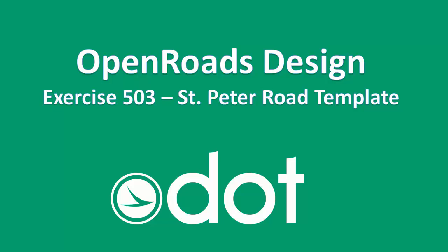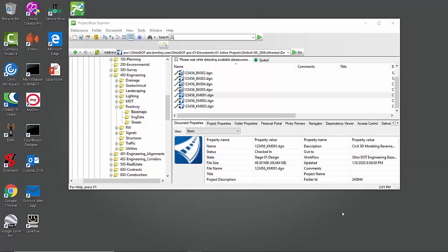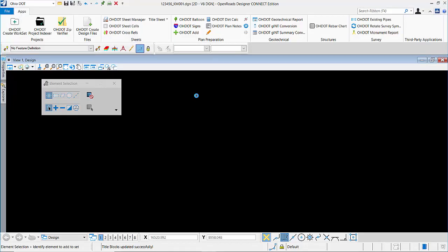This video is for the Ohio DOT Open Roads Designer Training, Exercise 503, creating the templates from some components that are already defined in ODOT's library. So I'm going to get started by opening the KM001 design file. And the file that I open really doesn't matter because I'm not drawing anything in this file. I'm just going to use the Create Templates dialog to create some templates.